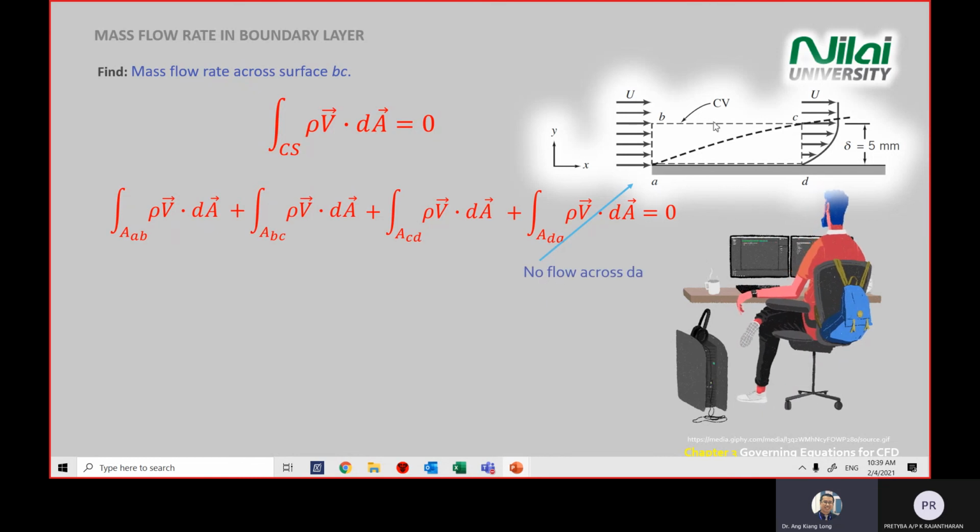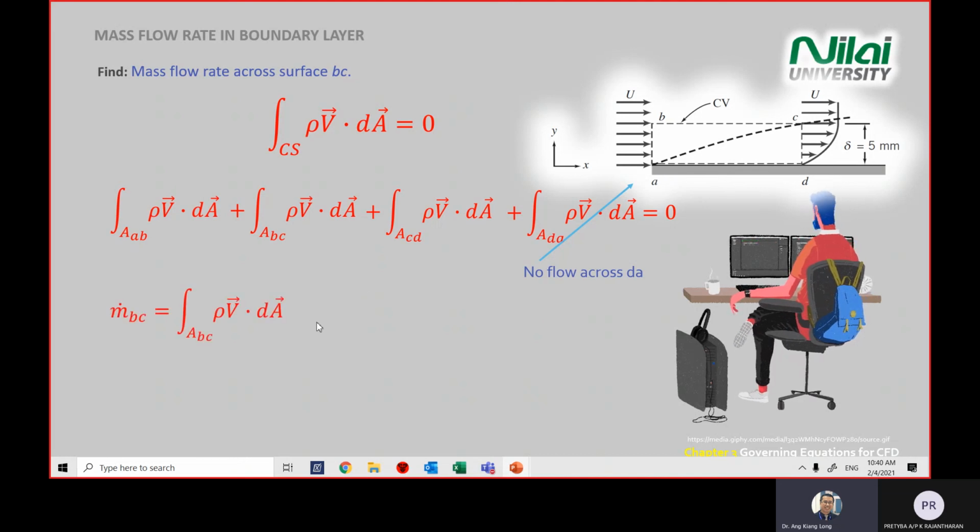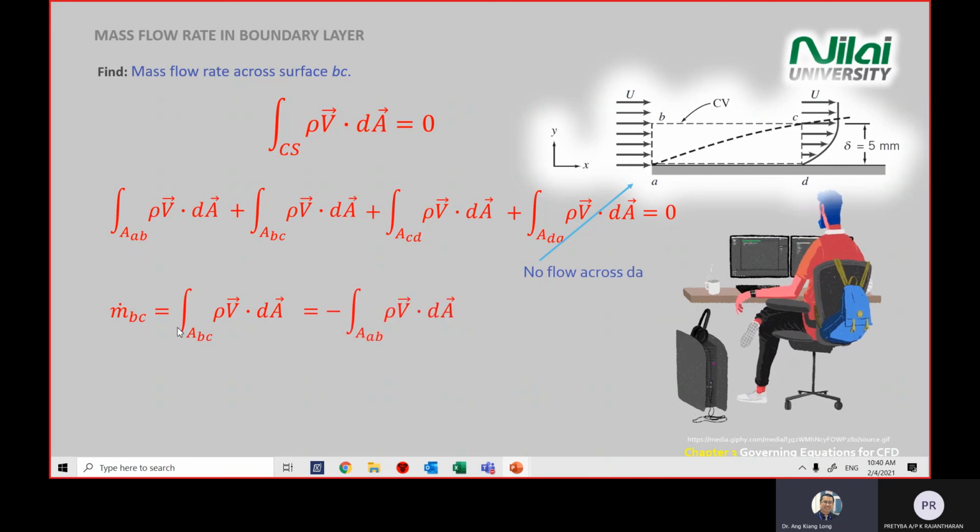Okay. And of course, in ANSYS, when you set the boundary layer and you set that there's a contact at a certain surface, then it will automatically calculate for you. Of course, in the simulation, you will see there will be some flow value or magnitude just above the surface. But along the surface, the contact, you will get 0 value along the surface if you set the no slip condition in the simulation. Okay, then yeah, the rest is just calculation from there.